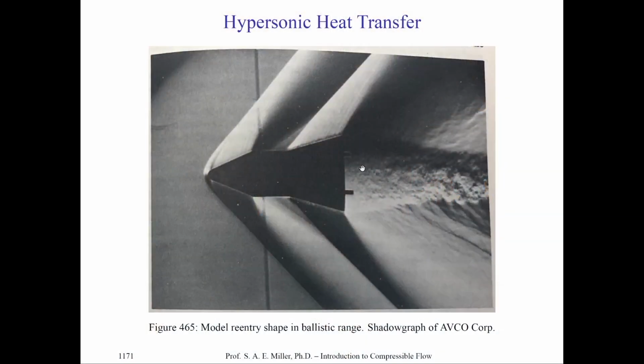The aft frustum of the vehicle, which is the portion of the cone or pyramid that remains aft of its upper part, has been cut off by a plane parallel to its base, in that it's intercepted between two such planes. And this provides aerodynamic stability. Let's look at that in the previous photo. You can see here's this initial cone, which comes back to a cylinder and brings back again another turning angle. This is done for aerodynamic stability of the vehicle, which is another subject of hypersonics, of course.